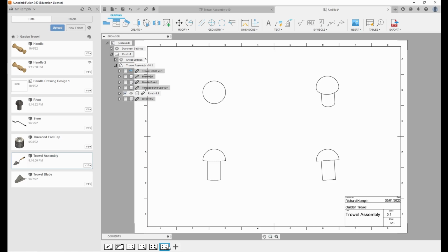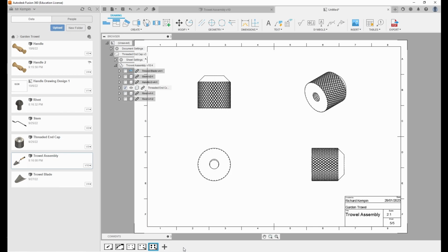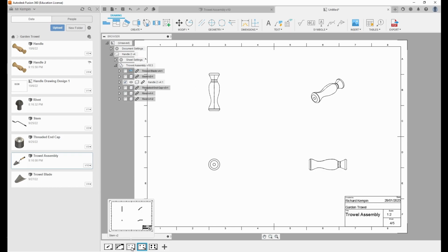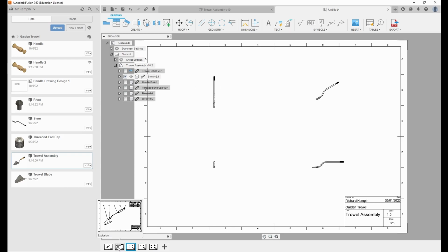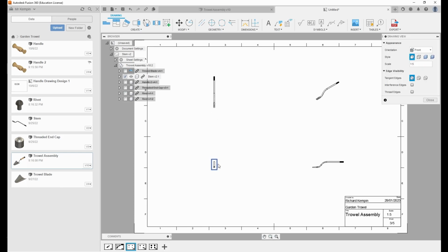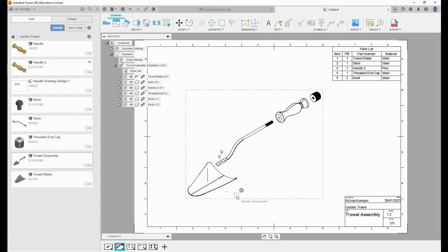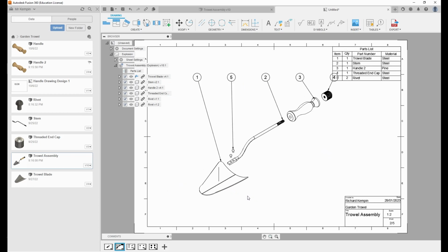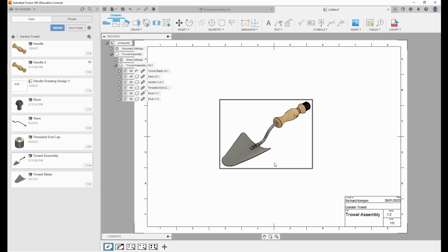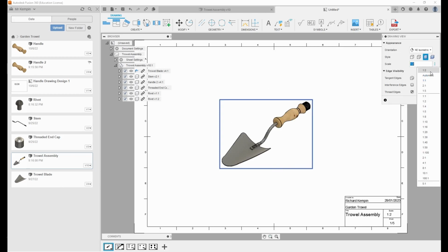And if there's anything you don't want, so you can see there's a sheet 1 of 6. Well, you know what? I don't think I need a technical drawing for a rivet. I can right click there and delete sheet. Well, now it's sheet 5 of 5. So this is automatically done for you. So this block now is all done, all set up, haven't got to touch it. And we can go in and start doing the measurements and any other things we need to change on this drawing. So again, remember for this one, I'm changing the scale from 1 to 1 to 1 to 2. Very nice. This one I might move that over a little bit, maybe more centralized. That's better. This one again, I've made that a bit bigger. I'll go full scale 1 to 1.